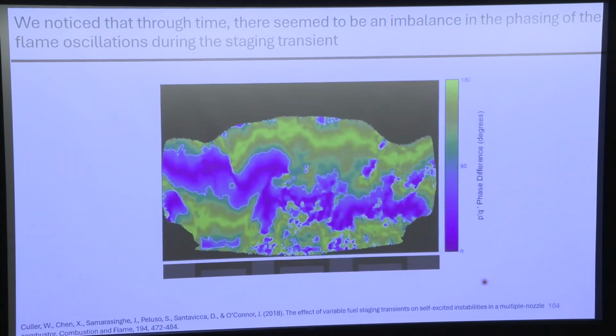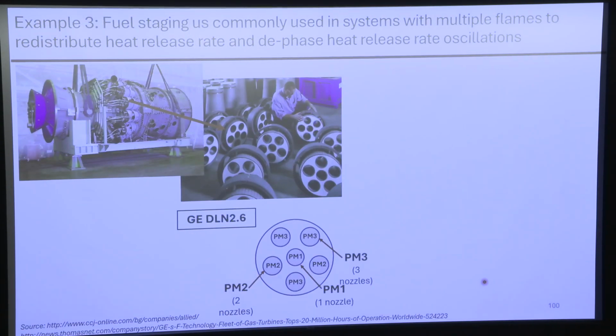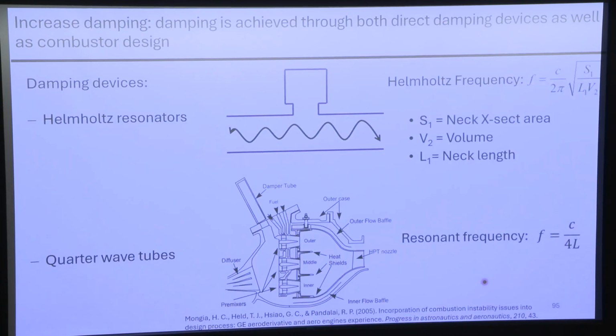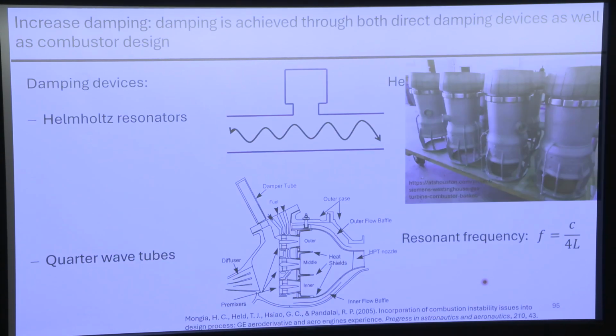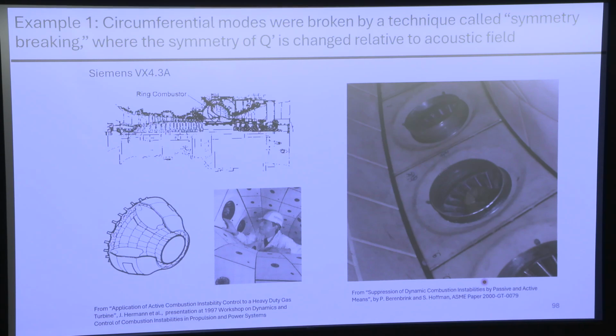We just saw a combustor that a man could fit in. Where's that picture? Ah, I lost the man. Where is he? There he is. This is probably a 400 megawatt engine. Let's say on order of magnitude, it's 50% thermal efficient, which it's not. It's probably less. That's 1,000 megawatts of heat you're putting in. There's no actuator on Earth that's going to be able to control that level of heat release rate reliably over a long duration of time.